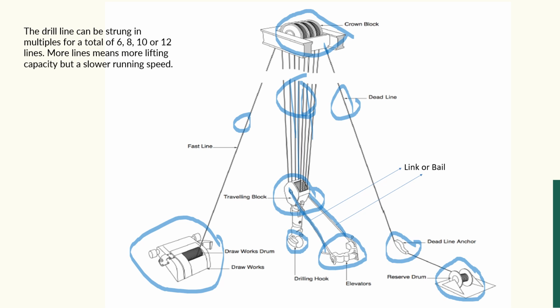Okay, so at the time of the slip and cut operation, when there is stress and wear in the drill line, that is done according to the ton-mile calculation.